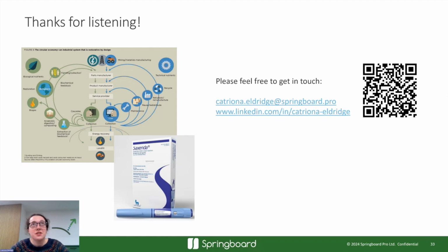Well, there's two approaches you can take there. I'll start with the one where we dispose of the item. And basically, yeah, taking the label off is your best bet. The label itself is going to be a real mixture of things, probably two or three layers of polymers stuck together, then your adhesive, and then also everything that's been printed on, so quite a few different inks. That's not really recyclable at the moment. It would have to go into chemical recycling. It's probably going to end up in landfill. The bottle itself is likely to be a bit more recyclable. It should have its polymer group mark on it, which should help you with that.